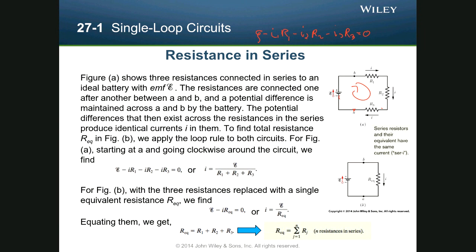If this circuit is in series, then the current that's established from all the resistances and the EMF is the same. All right? So we in fact don't need I1, I2, and I3. We can simply rewrite this equation as I R1. This one will be I R2. This will be I R3.